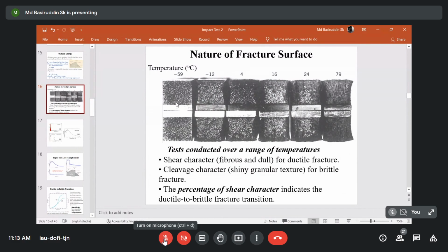Then this crack length will gradually increase, and it reaches a final length where the specimen thickness is reduced significantly. Residual portions will be there, which decide the state of stress, that is the plane stress condition. So at the end, no triaxial state of stress will be there, but plane stress conditions will be there, and that leads to failure under shearing mode.